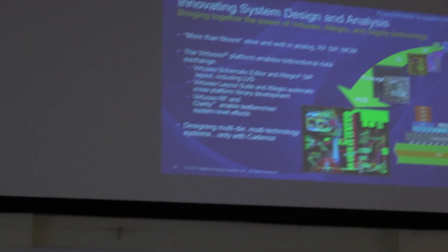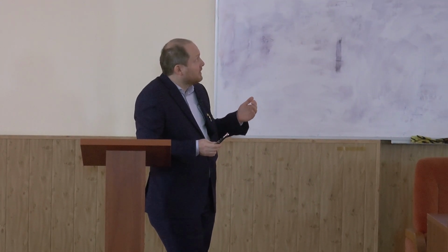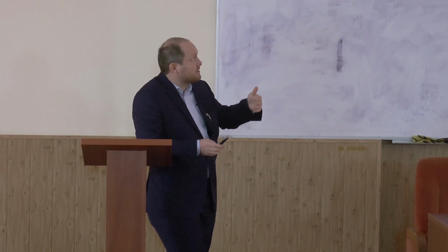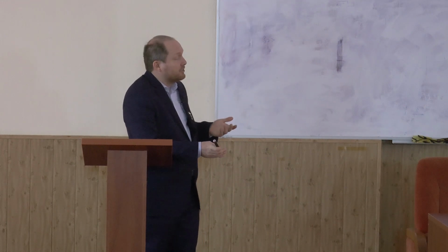Here we have a number of integrated software tools, so you can extract all the parasitics on the board, and all the parasitics on the package, and then simulate these parasitics together with your chip to see if the specification is still met and the chip is still working as planned.